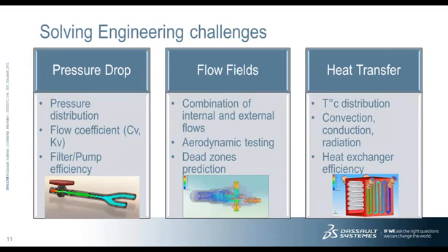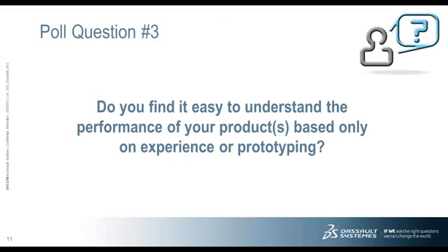With SolidWorks Flow Simulation, you can simulate fluid flow as well as couple it with heat transfer, such as convection, conduction, and radiation. Designers can apply heat sources, thermal properties on components, define fan positions, for example, and then get as a result the temperature distribution, both for the fluid and the product itself. So these are typical applications, but obviously SolidWorks Flow Simulation is appropriate for many more applications.